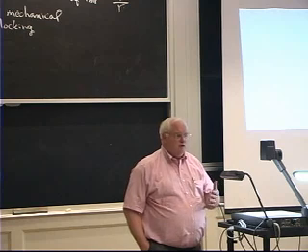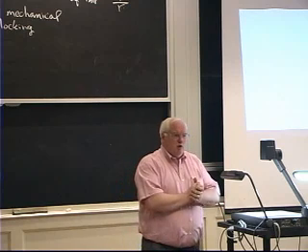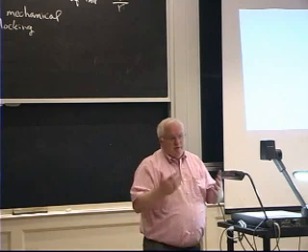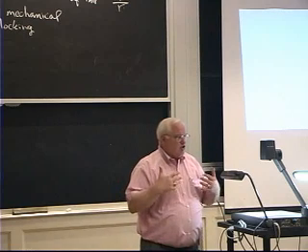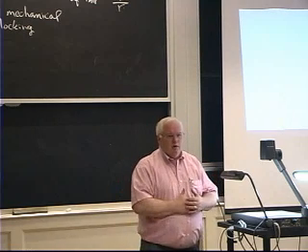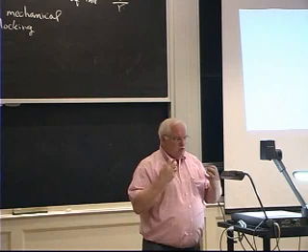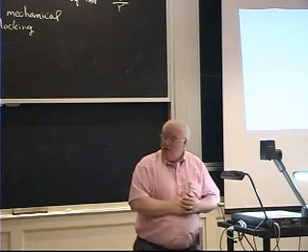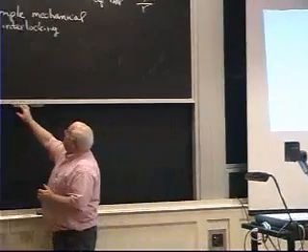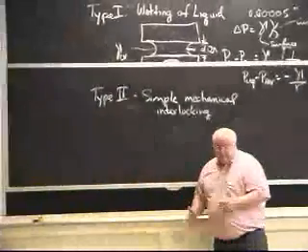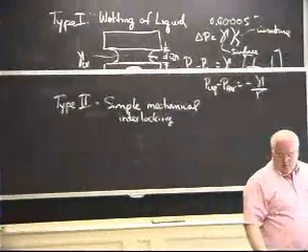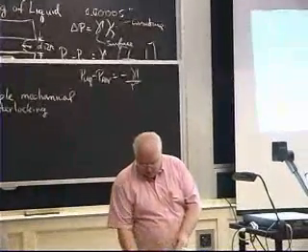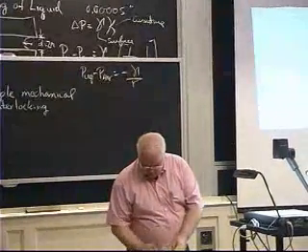You've got a smooth surface, and your adhesive is really working by type 2 mechanical interlocking. You need to chromate it, you need to phosphate it, you need to anodize it, you need to do some type of surface conversion coating to prep the surface to make it rough, to get good type 2 mechanical interlocking. Now, type 1, in general, you don't want a rough surface. And I thought somewhere in here.